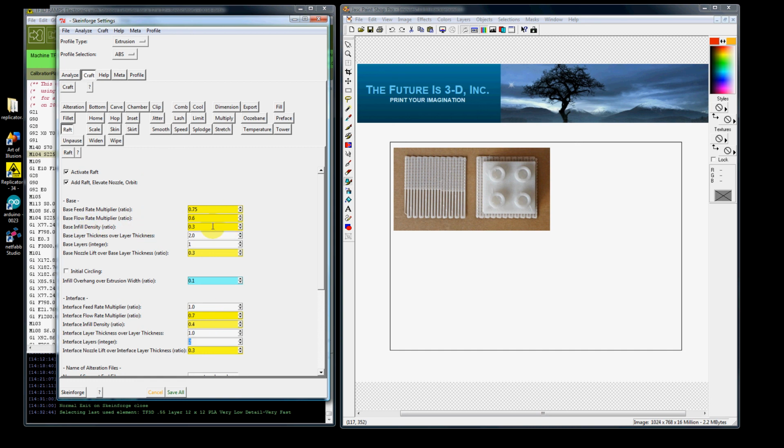So the settings that I have here do put down a very nice base. You can see that on the Glacier Steel website where I show printing the fan bracket. It's a huge raft for a huge part, and it really helps. I try to refrain from using rafts as much as possible. With the Kapton tape and our extremely flat bed, it doesn't warp, it doesn't come off, doesn't have any problems. I've printed huge parts without that warping.